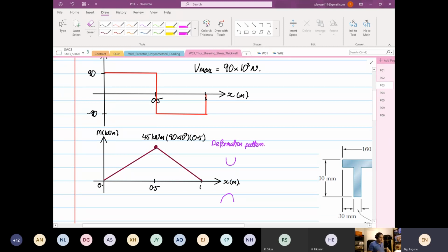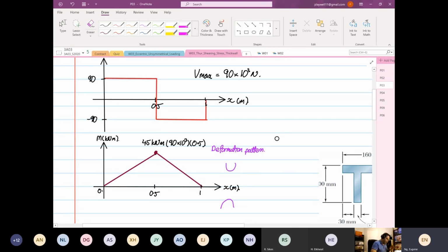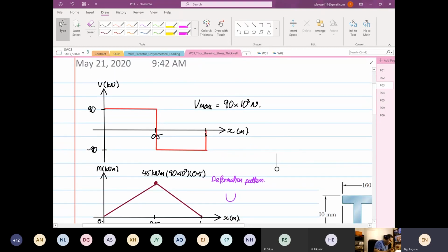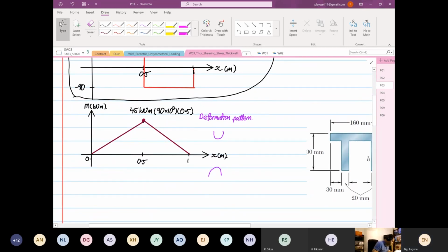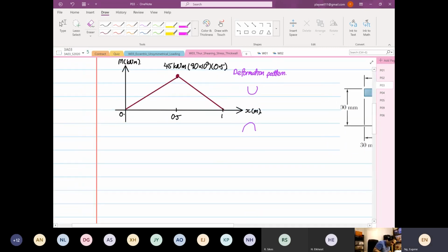Okay, but for this course, or for what I'm teaching now, we are only going to focus on here. So later, when you are given a beam that has multiple loads, point and distributed loads, you have to draw this diagram, and you have to find what your Bmax is. That's the important thing, right? So from here, we are going to calculate our shearing stress. We're going to calculate shearing stress now.